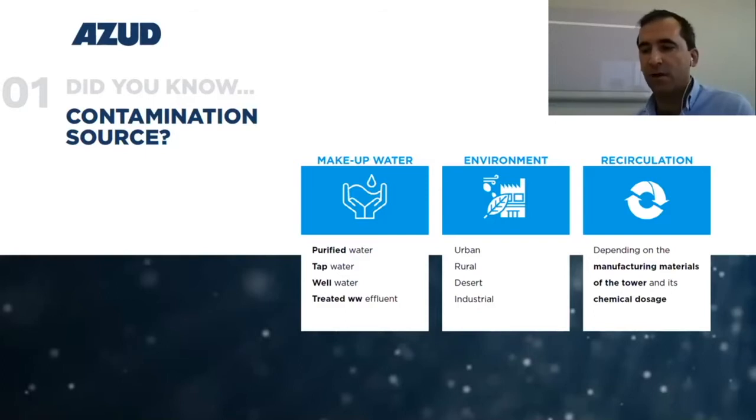For example, in the Middle East, sandstorms are very frequent, so they can increase the suspended solid levels in the refrigeration circuit. Also, the installation itself can be a contamination source, as pipe degradation by high and constant chemical usage will release suspended particles to the circuit. So all these particles can eventually decant and affect the water flow and therefore the heat transfer of the cooling system.